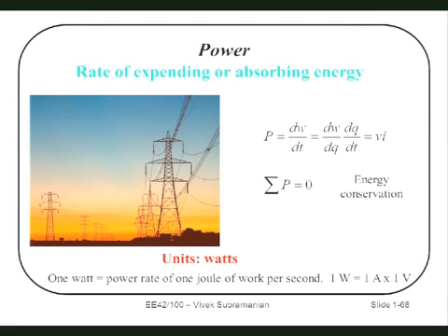Okay? But remember what W is. W was related to voltage, and W was related to current, and W was related to time. So, let me rephrase that. We have related W to voltage and to Coulomb charge. But remember what coulombs are. Coulombs are the integral of current, right? So it's with respect to time. So I can write dW dt as dW dq times dq dt. Because dW dq was voltage, and dq dt is current. So then power is just voltage times current.